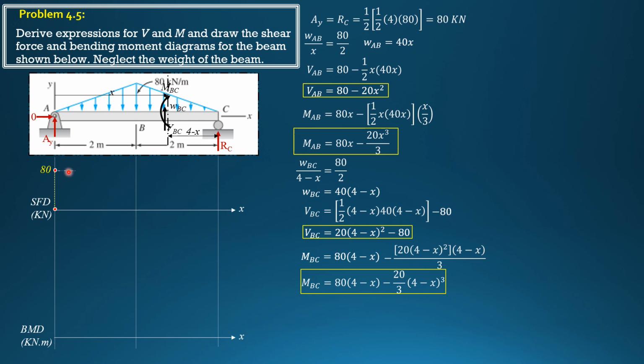By the way, the other way of defining the curvature of the curve, because this is second degree curve, is to put the initial slope. Later, the intensity of the load is the slope of the tangent to the shear diagram. So this is an additional technique. Because the intensity of the load here is 0, the slope is 0. The intensity of the load here is negative 80, and negative 80 slope is up to the left like that.